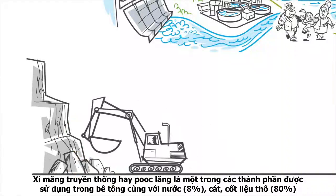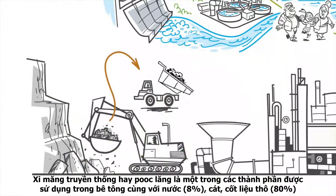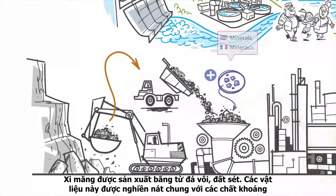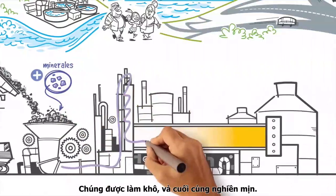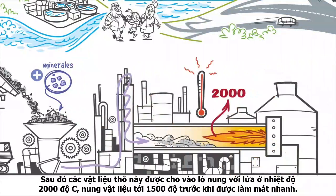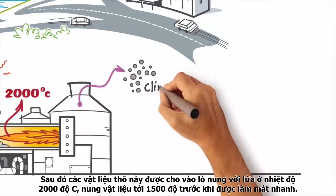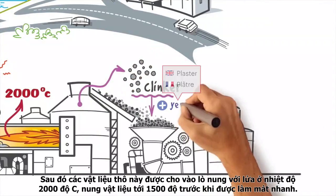Traditional cement, or Portland, is one of the components used in concrete, along with water 8%, sand and gravels 80%. It is produced using limestone and clay. Such rocks are crushed together with other minerals, then they are dried and finally ground. This raw mixture is then put into the oven, where a flame that reaches 2,000 degrees Celsius takes the material to 1,500 degrees before suddenly being cooled down.